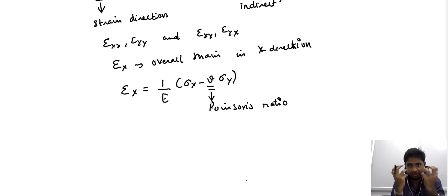It is introduced by the stresses along the x-axis and also the stresses along the y-axis. That is, under the biaxial tensile loading condition, both the loads that we impose along the perpendicular directions contribute to the strain in a particular direction.